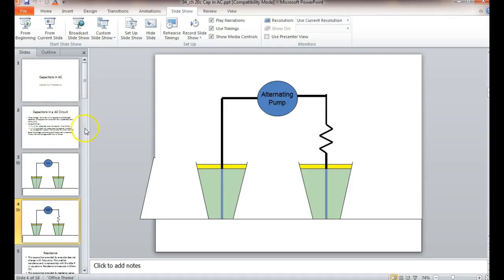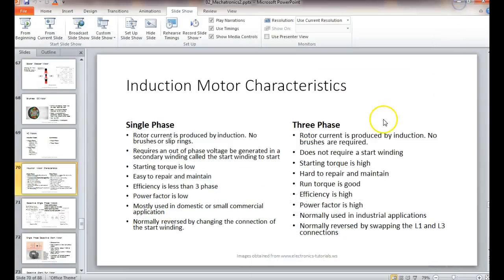Now when something's in motion, it wants to do what? Stay in motion. So on single phase motors, we create a phase shift to start the motor. And then when the motor starts running, we switch that phase shift out. On a capacitive start motor, the start winding is not very expensive. It's not made to stay in the circuit very long, so we don't have to have a lot of copper in it, right? You understand that?